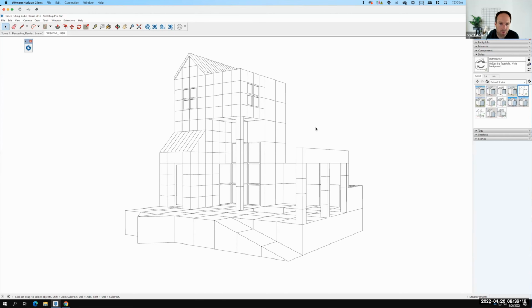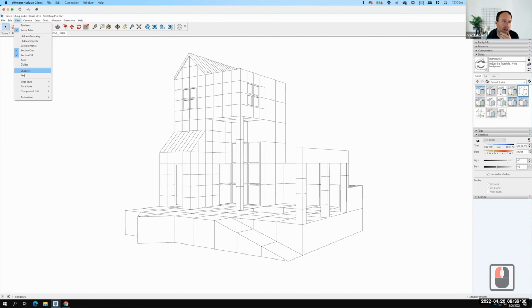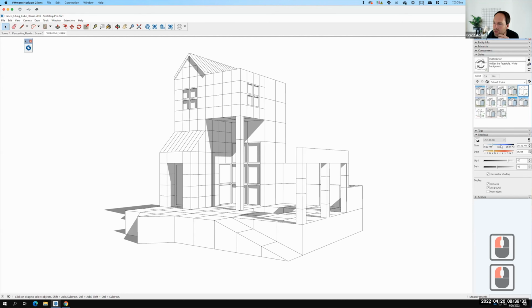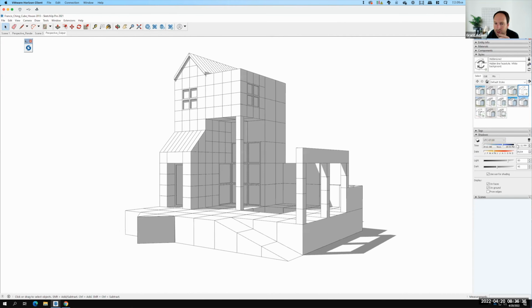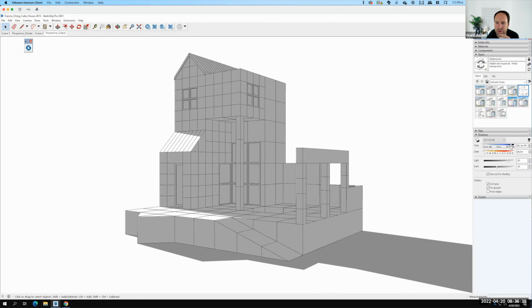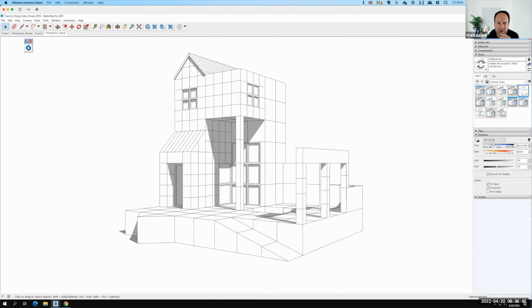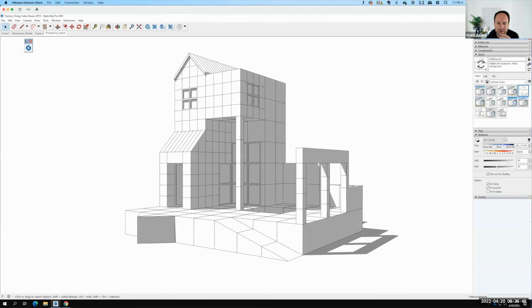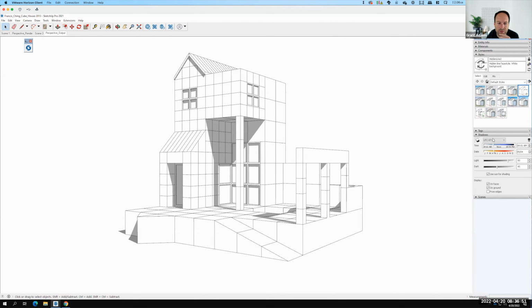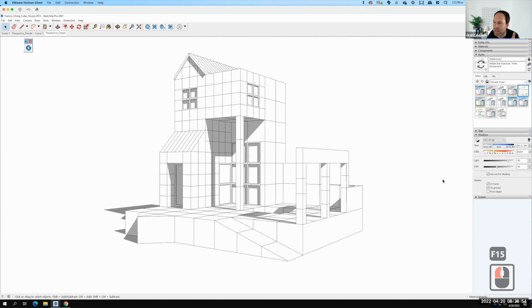Now the next piece would be to do an export that includes the shadows. So the shadows, if I open the shadows drawer on the right here, we can actually choose a specific date or time for the shadows. So let me go to View, Shadows, and then I would move the time to get a set of shadows that looks good. Obviously, picking a set of shadows where your whole building is in the shadow might not be the best. So you're going to find something where you kind of like the shadows, right? And you can flip it around. You can decide where you want those shadows to be. Or if you wanted it at a specific date and time, you could set it for that specific date and time. So there it is. I have my shadows set up.